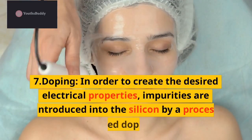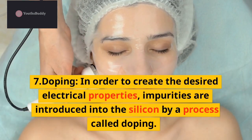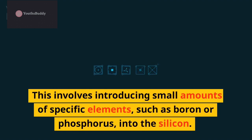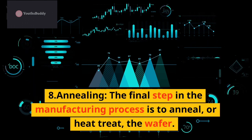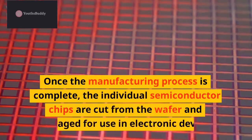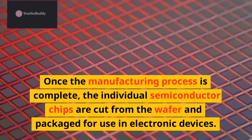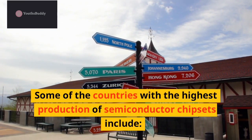7. Doping. In order to create the desired electrical properties, impurities are introduced into the silicon by a process called doping. This involves introducing small amounts of specific elements, such as boron or phosphorus, into the silicon. 8. Annealing. The final step in the manufacturing process is to anneal, or heat treat, the wafer. This process helps to activate the dopants and create the desired electrical properties. Once the manufacturing process is complete, the individual semiconductor chips are cut from the wafer and packaged for use in electronic devices.